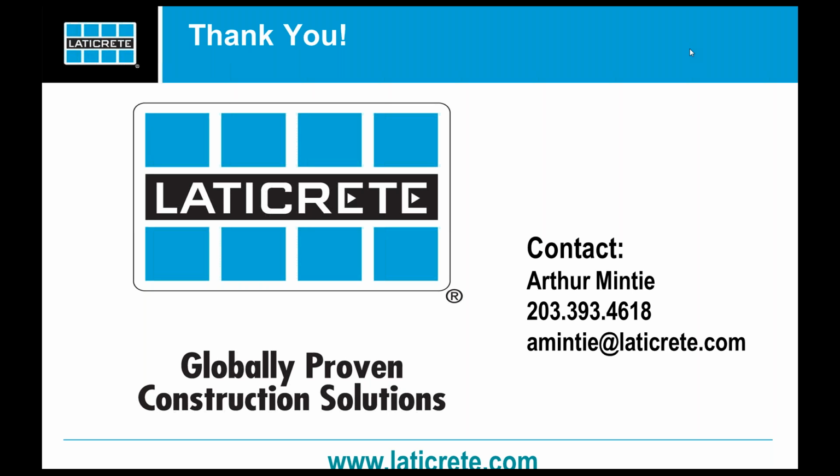Yeah, it's a great question. We do get that, and it really is a tough question to answer. From what we've seen, it does take a little bit longer to install those large gauged panels. Usually, if it's a panel that's larger than, say, 3 foot by 3 foot, or a meter square. If it's a meter square or less, you could probably use your standard labor rates. But if it gets to be larger, any edge larger than 3 foot, it's probably going to take 30% longer, maybe even 50% longer from our experience, what we've seen.